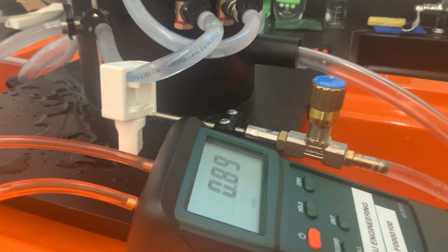So at this flow rate, at this major head loss, I have to again collect the water flow given a certain time so that I can measure the flow rate, and from there I can measure the fluid velocity because I know the cross section of the tube here. So we have to repeat this test 4 times and we'll be done with the data collection for the high flow rate. Now we'll move to the low flow rate.